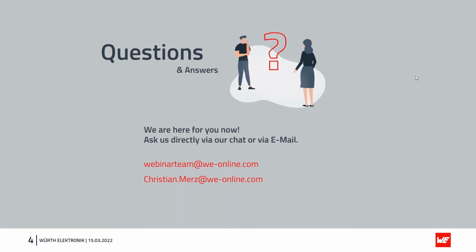Perfect. Okay, then I think we still have some time for some more questions. Christian, are there any recommendations you have on an integrated wireless receiver IC to use? Well, it depends on your application and on your power, and if you need, for example, a Qi certified system. For Qi, there are many different wireless receiver ICs, and of course, you also need a transmitter IC which is Qi certified, and you have to fulfill the standard. But if you do not need the Qi standard, you can also use any other IC from TI or Analog Devices, depending on your application. For example, when you want to load a battery, there are some very good battery charger ICs from Linear Technology or Maxim or TI. I can send a list afterwards per email of some very good ICs, where also some simulation models are available.